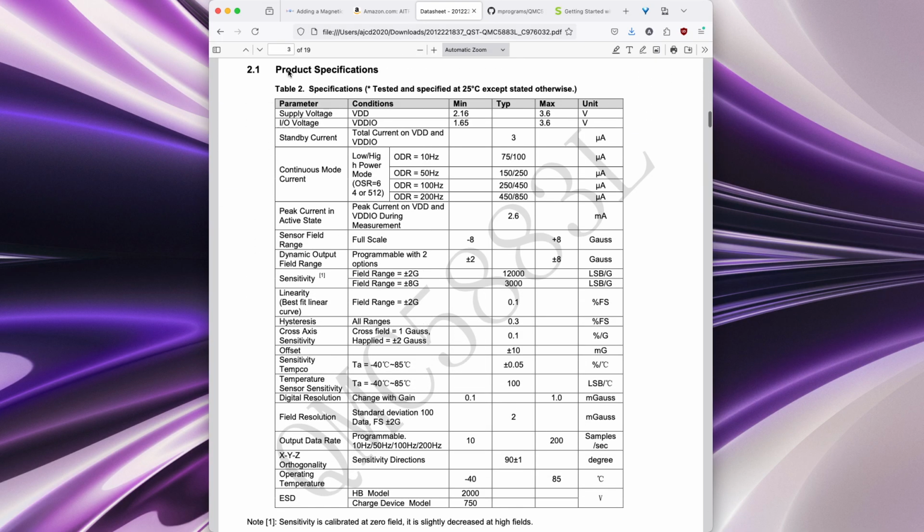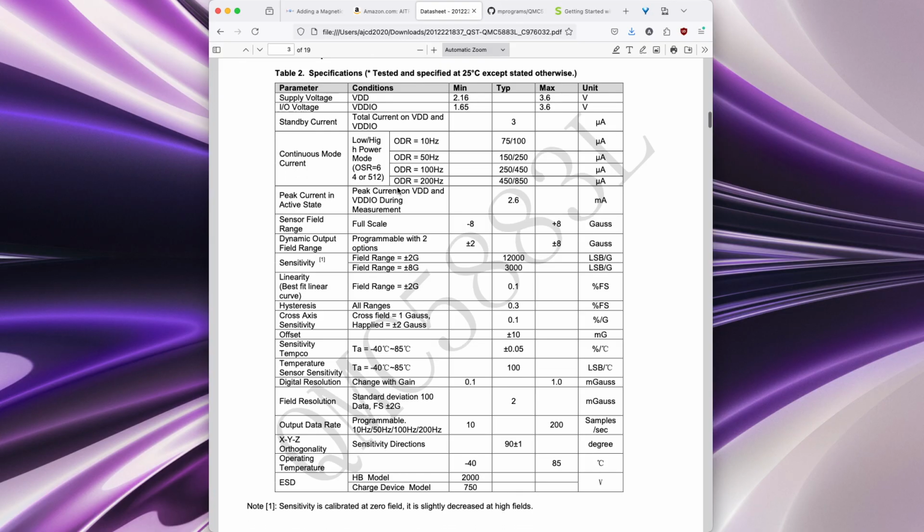The next thing to look at is the specifications table here. It says the range for the supply voltage and the range of the input-output voltages. So those are slightly different. Supply is what we're plugging in as power and ground, and I/O gives you a range on what it considers possible for registering a value as a logical high, meaning 1, and a logical low, meaning 0. The rest of this gives some information on temperature and hysteresis.